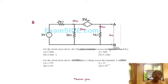a short through the voltage source. So in total, the 2 kilo ohms also gets shorted, or in other words, the current that emerges from the 5 volt is going to be 5 divided by 2 kilo ohms, which is 2.5 milliamps. So 2.5 milliamps flows through the short circuit, and that becomes the Norton's current. So Thevenin's resistance is 0.5 divided by 2.5 milliamps, which gives you 0.2 kilo ohms, which is answer B.